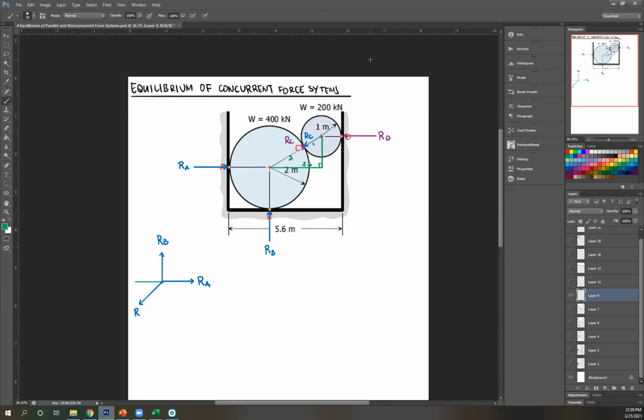So remember, whenever we're given slope, we have the choice of using that slope. Or if you don't want to do that, you also have the choice of just figuring out the angle. And that is what I'm going to do so that you can also learn that technique. I'm going to figure out the angle of this right triangle, which is also the same as the angle of my force. So once again, let's draw that right triangle. This is 2 and 1, therefore this is 3. This is 2.6. This is your theta. Using cosine, cosine theta equals adjacent over hypotenuse, 2.6 over 3. Therefore, solving for theta, you get 29.93. Correct, Skylar and Nicole.